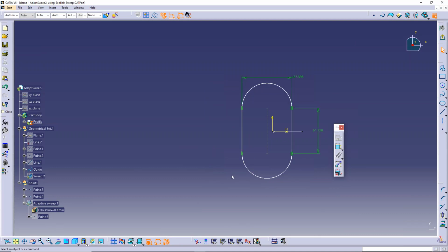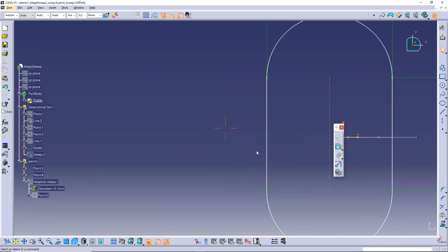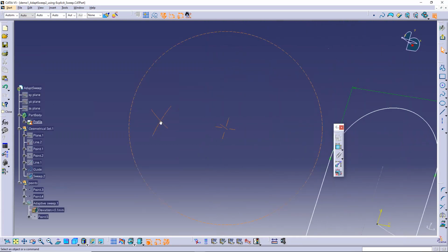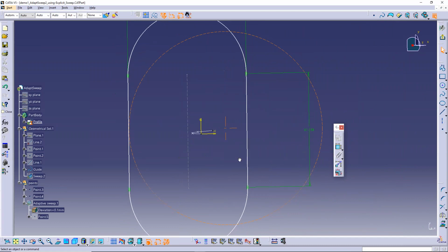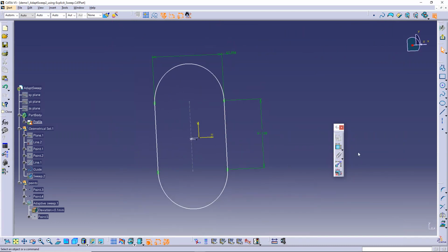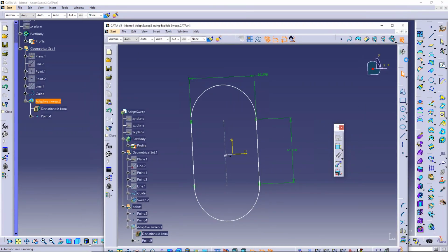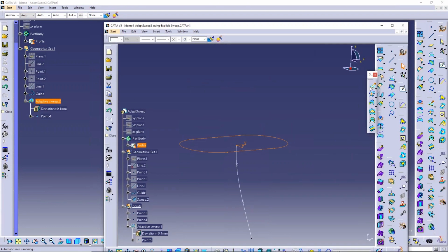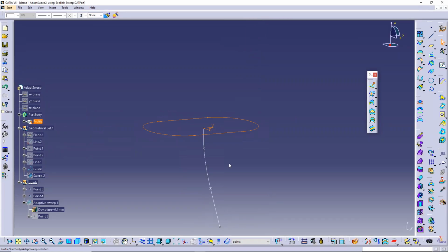Get rid of that one there so that we can fully constrain with no distraction. So in addition to some of the conditions that you see, tangent and collinear there, we do have some dimensional values there sizing out our shape. Now we'll go back over here, coming out, hide again, of the workbench. And you know what? Now that I've got this, let's make this bigger.